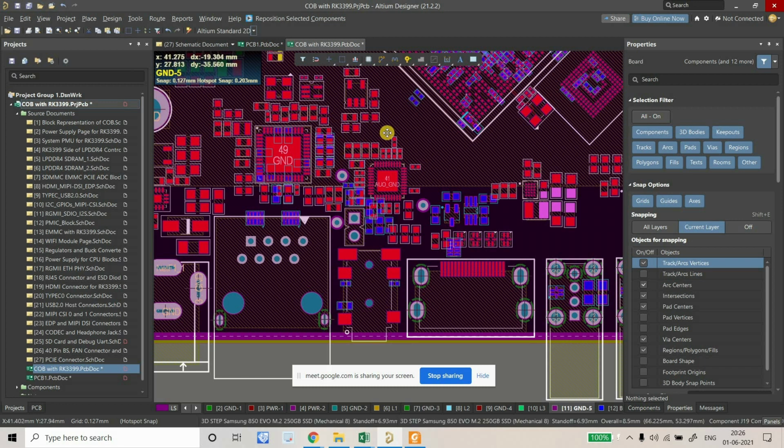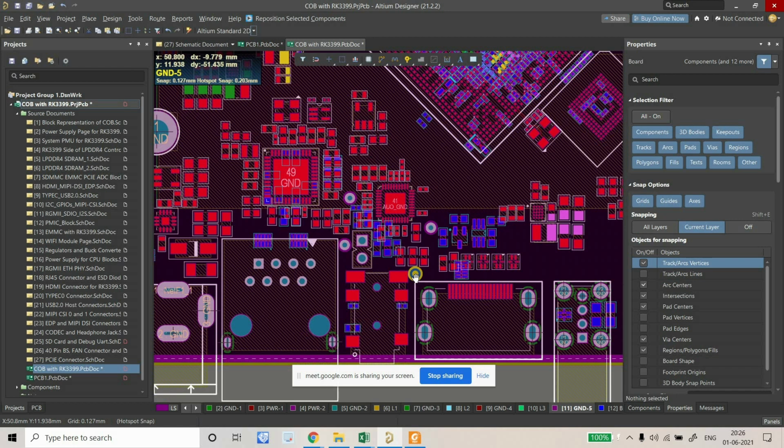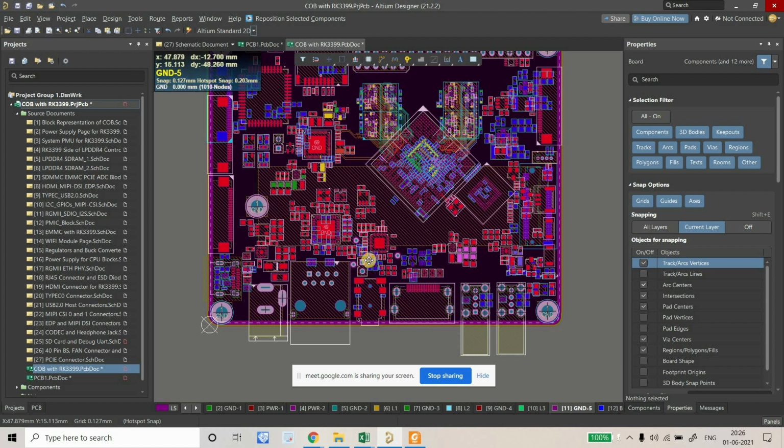Okay, so that will create the isolation on the ground planes. That I will demonstrate in very much detail when I record everything. But yeah, that you have to plan. Another thing is to just completely isolate this, completely remove this section.